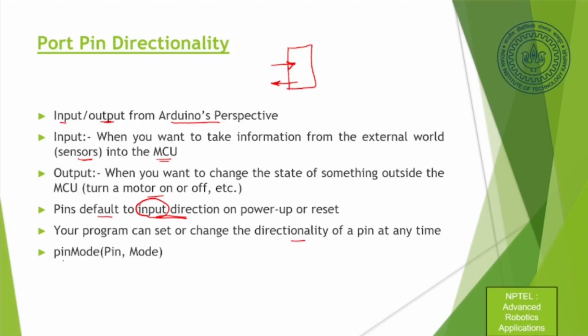And how do we do that? The syntax of the program line is very, very simple. It simply says pinMode, then the pin number, and this is the mode, input or output. So it is very, very simple to set.